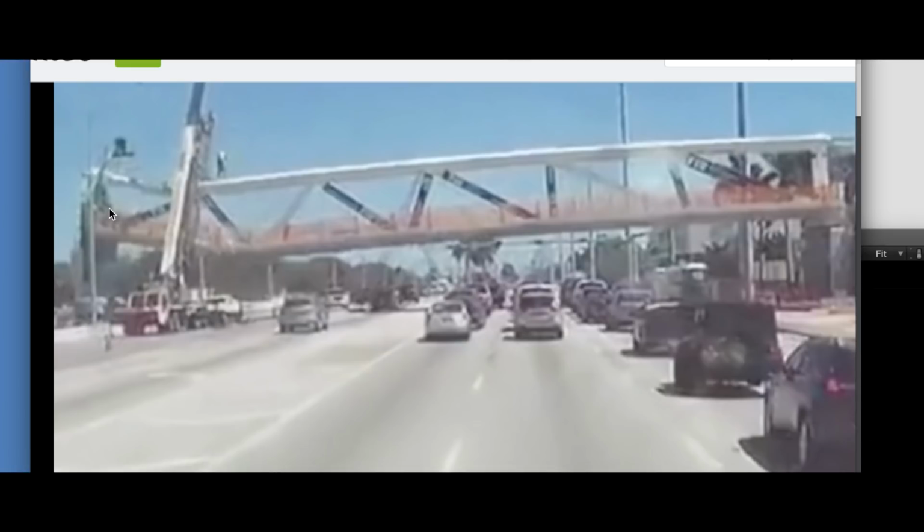So as we look at this, we now have this still on the deck. If you run your chain from here, it is now turned inwards a little bit. Your chain here was here, but your distance from here to here was here on the deck. Now your chain's gotten shorter and it's here now. You've got loose links. That means it's now pulling this apart, but number 11 is still acting as a jack, if you will, holding back some of this 12, and this is where it's not quite deteriorated.